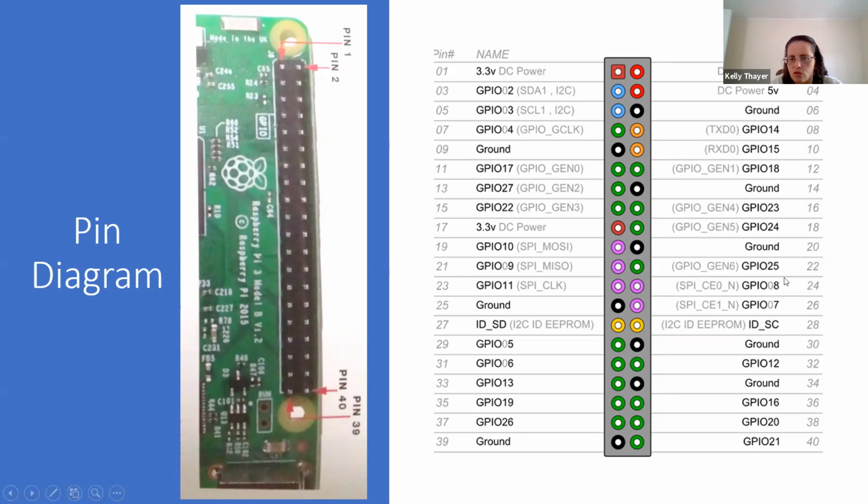So we're actually going to use GPIO 25. Not that there's a specific reason why you have to use this one, but it's on the outside of the board, and it's right in the middle, so it seems like a good one to pick. The signal to turn your light on and off, turning that electricity on and off to run your circuit, will happen over the GPIO 25 pin, which is in position 22.